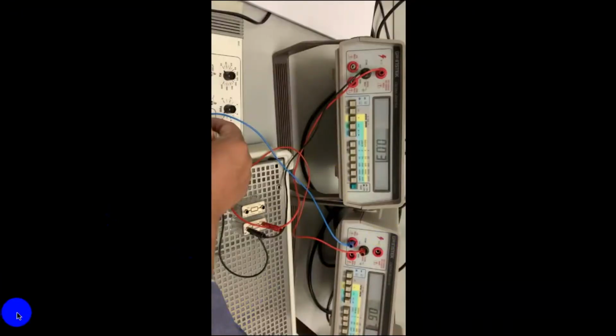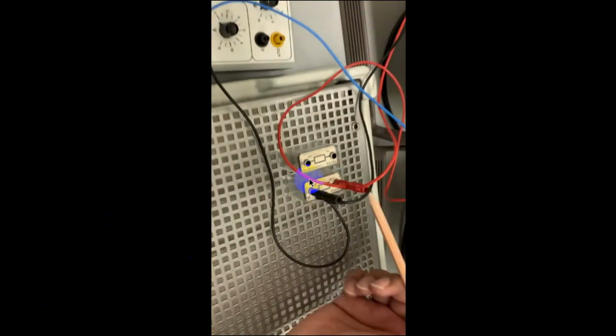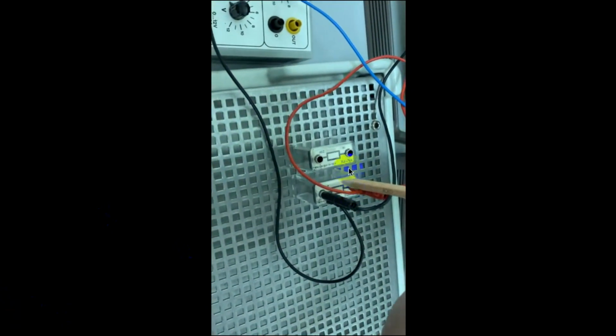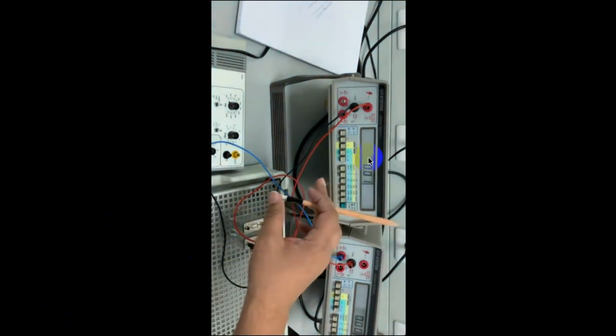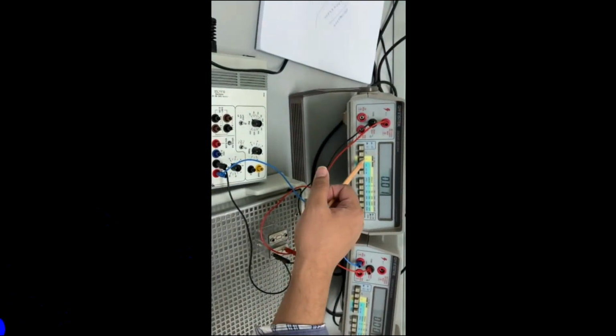Now accordingly we have changed the resistor from 1 kilo to 2.2 kilo. So just remove from here and connect it here. From here just make the connection like this. Now our resistor value is increased to approximately double, 2.2. Now if I give 2 volt as input voltage, the current will be approximately half, because the resistor value is increased, so the current will decrease accordingly.